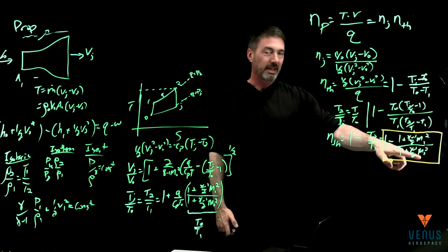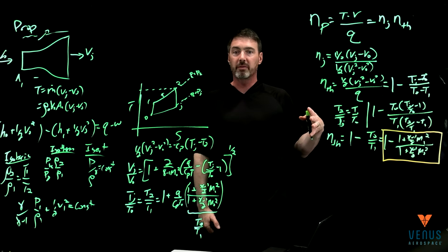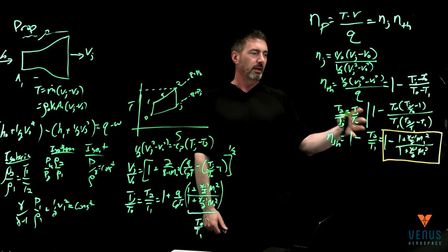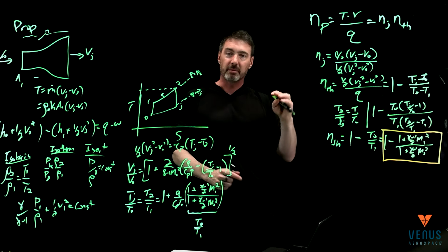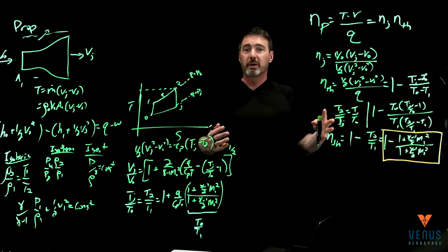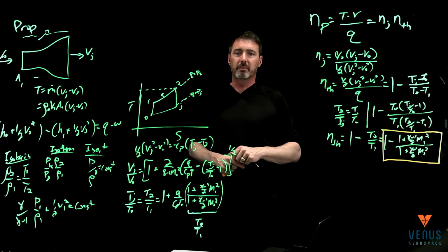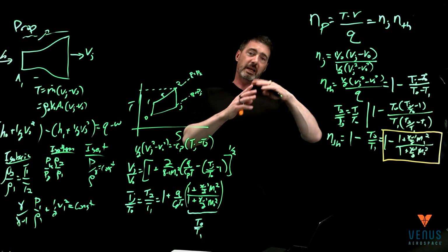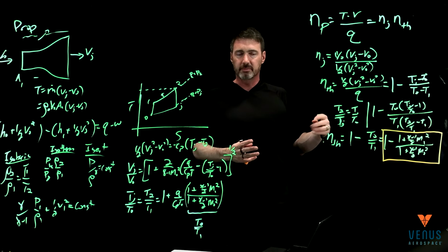This is as your free stream velocity changes. If I want my combustion speed to be Mach 0.5, subsonic, then this says that my thermal efficiency is going to get better as I get faster, and we know that. We know that at slower speeds, ramjets are really horrible propulsion systems. It's kind of Mach 3, Mach 4, Mach 5 and higher where they start being pretty awesome.